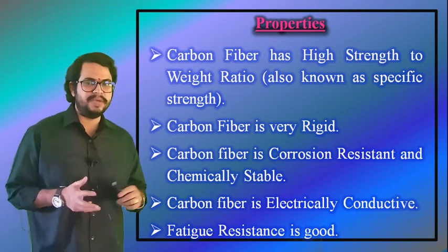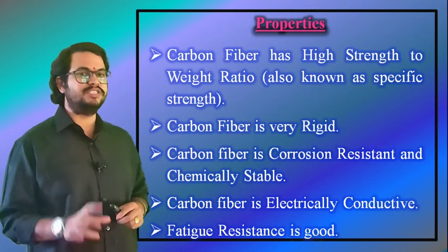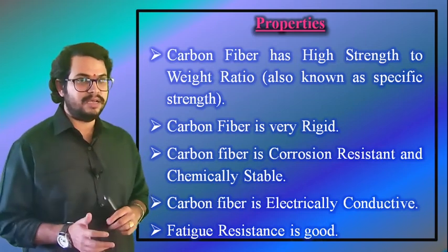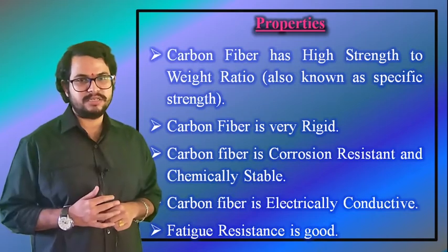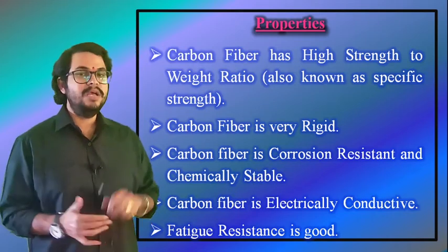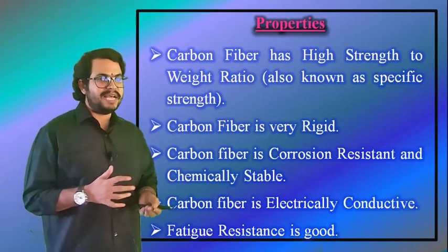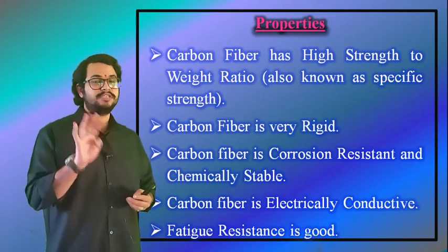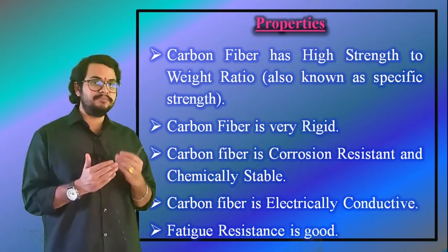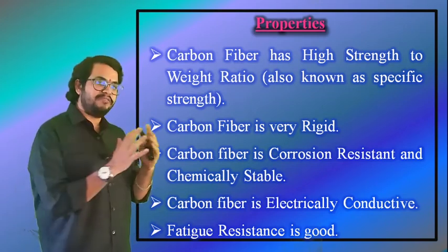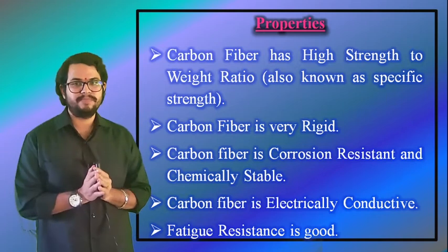Rigidity or stiffness of a material is generally measured by its Young's modulus, and it measures how much a material deflects under stress. Right? You might have already known. The carbon fiber reinforced plastic is over 4 times stiffer than the glass reinforced plastics. That means almost 20 times more than pine, 2.5 times greater than aluminium.